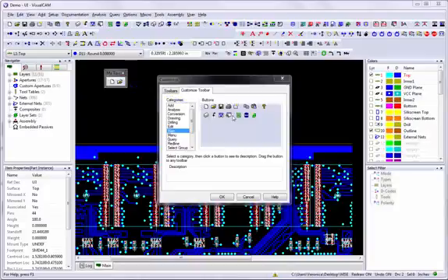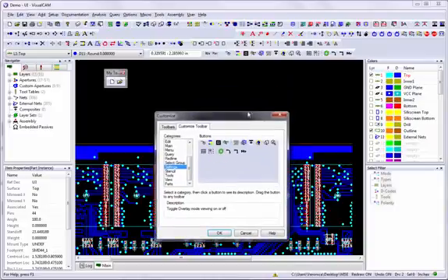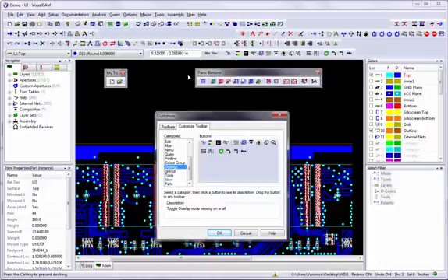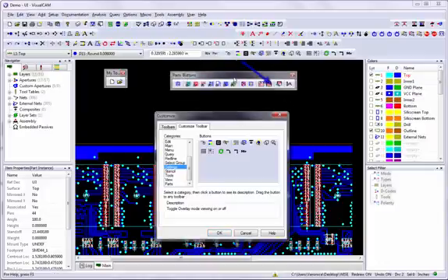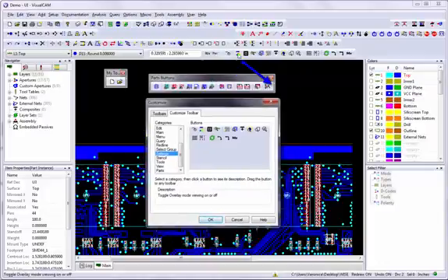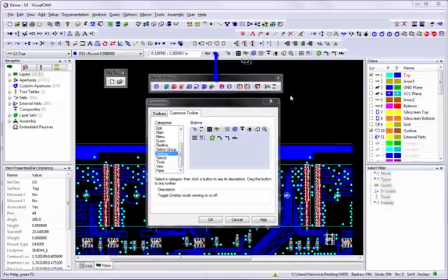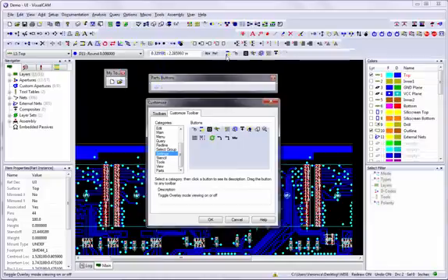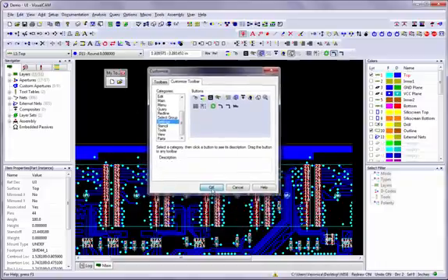Buttons can be moved from one toolbar to another or rearranged within a toolbar. For example, with the dialog box still open, drag the Toggle Overlay Mode button from the Settings to the Parts Buttons toolbar and drop it at the end. If you decide to move it to another position along the bar, left-click and drag it to its new position. Note that these changes can only be made while the Options Customize Toolbar dialog box is open. Once you have your toolbar set the way you want, click on the OK button to close this dialog box.